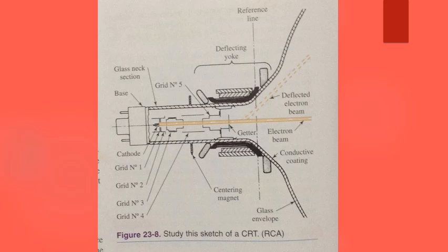The video signal adds to or subtracts from the bias on the tube. This action results in a modulated electron stream that conforms to the picture information in the video signal. The picture is produced on the fluorescent screen. The sharpness, or focus, of the electron beam can be adjusted by changing the voltage of the focusing grids. From time to time, they may require adjustment. Refer again to figure 23-8. Find the centering magnet. Slight adjustments on this magnet will correct a picture that is off center.